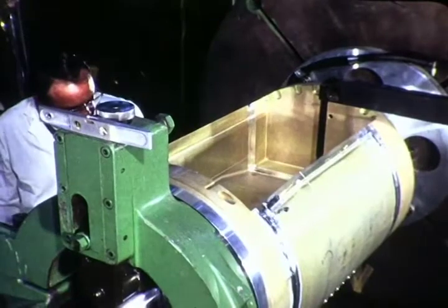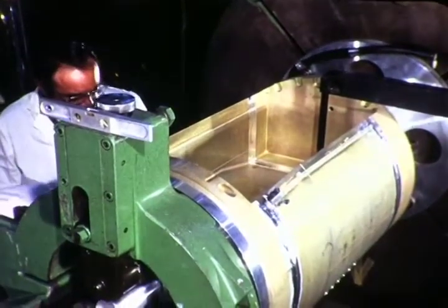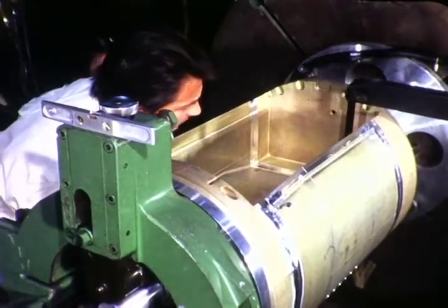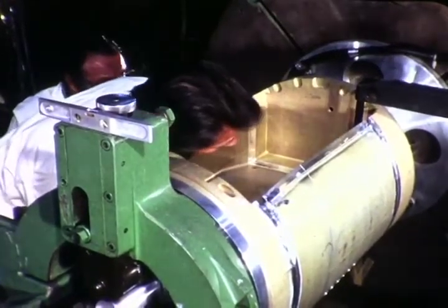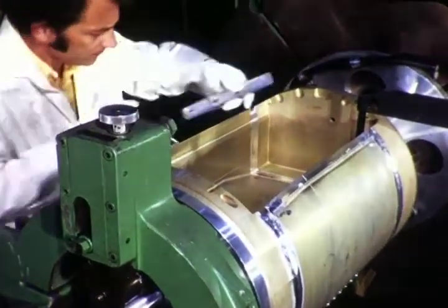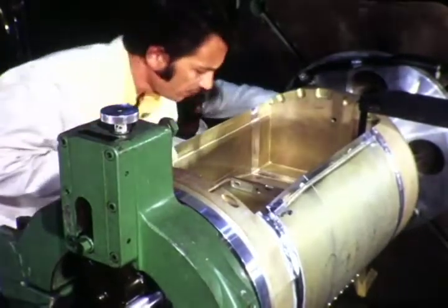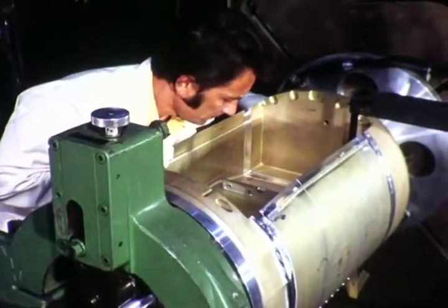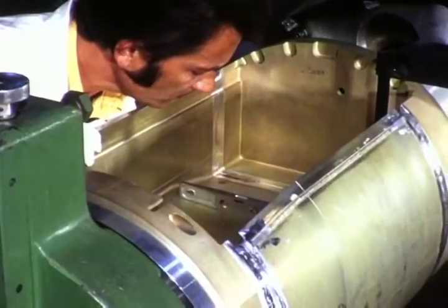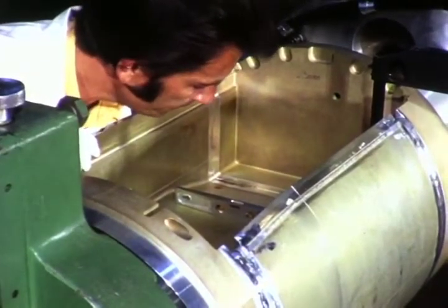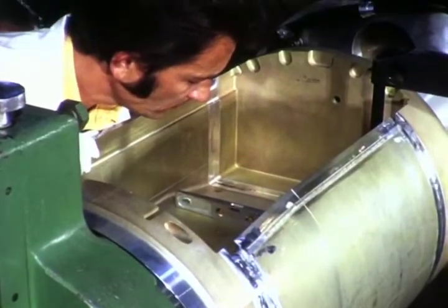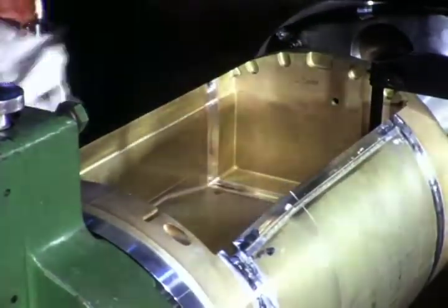A single key push rotates the turntable to its programmed starting position. The torch is then manually jogged into a position in touch contact with the side wall of the cavity. The part, in this case the aft body section of a subsonic cruise missile, is leveled across its flat internal cavity plane and clamped to the turntable. This operation, called the set point, establishes an accurate relationship between the torch and the part and sets all ram position data in the computer.